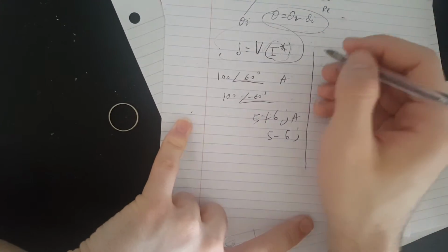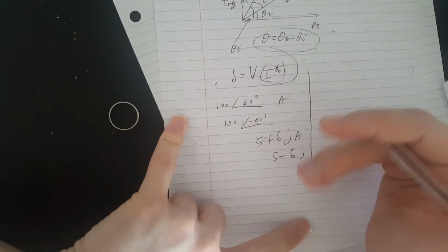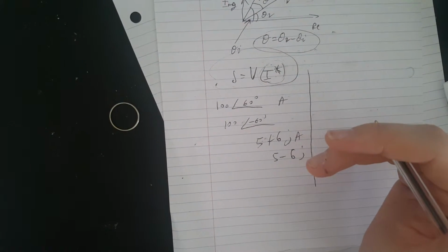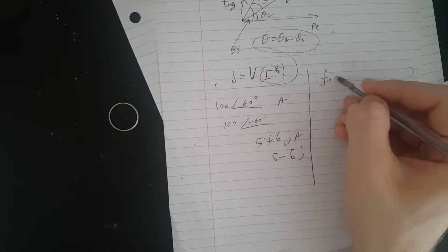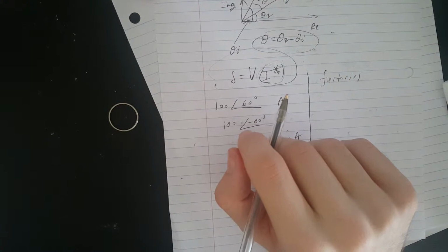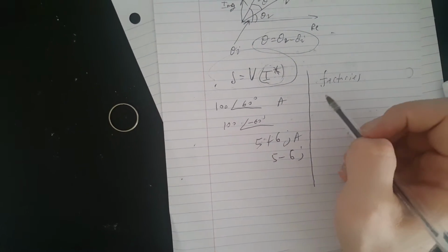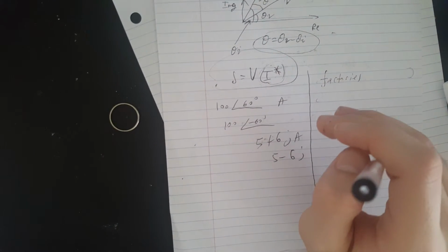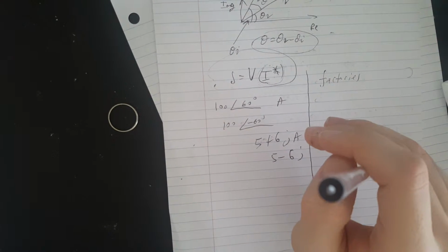Why do we care about apparent power and real power? I will go into more detail, but basically a power company has to care about apparent power because it affects how much current they have to pump out, since it's something they still have to supply. If you have factories, sometimes they've got inductive loads, and that really matters, and they have to charge them more for that. Usually the power companies install capacitor banks all around the grid to compensate for that. We will talk about power factor compensation later, and we'll do some examples on that.